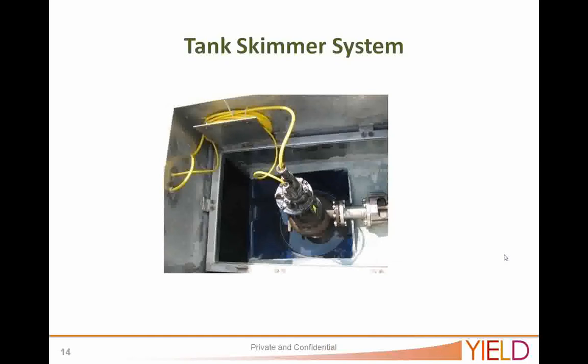And that's to take out the sinking fraction that's resultant from pre-treating a slurry. Then we also skim a fraction. The unique design that we have works in a gas-tight environment, so it's safe for that. And we are able to skim continuously the floating fraction off the digester.